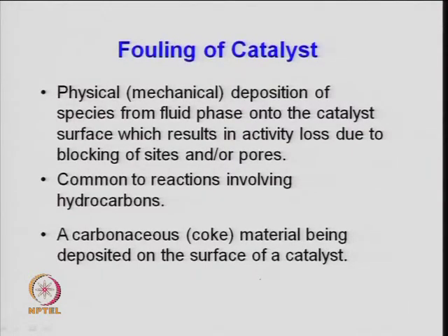Sometimes it may be because of the catalytic activity, that is, the acidic catalyst. Acidic catalysts have more tendency to form coke, so coke formation on an acidic catalyst will be more. If the feedstock itself is more prone to coke formation, then the catalyst acidity should be reduced accordingly.